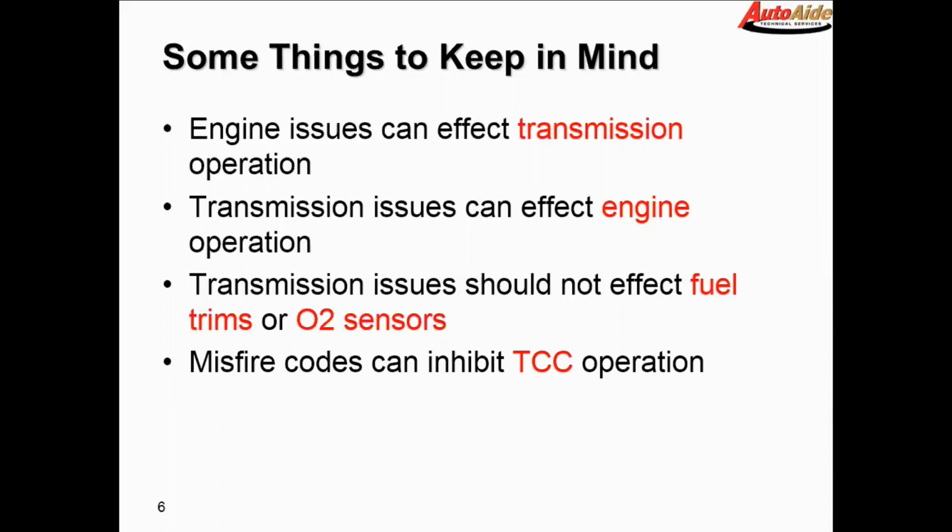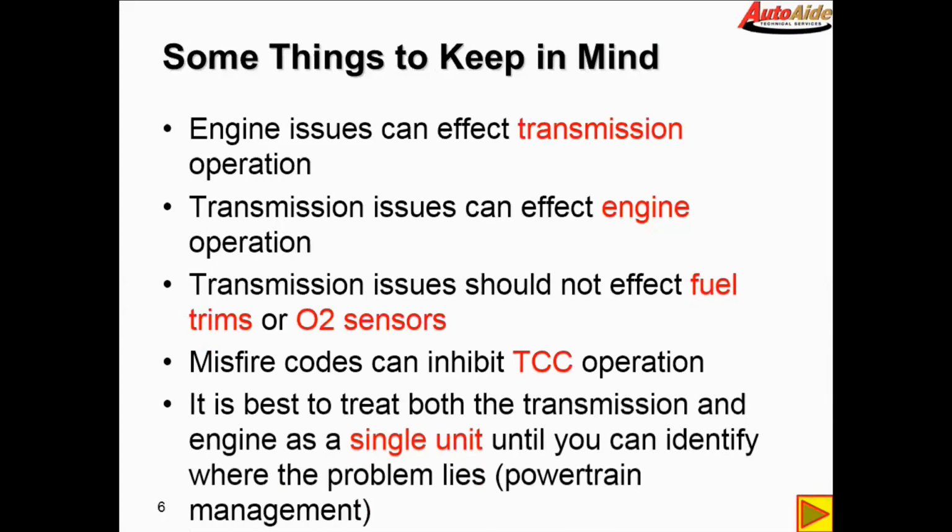Hopefully, if it's misfiring, it's going to set a code for that. But until you can separate out where your problem is, it's best to treat the transmission and the engine as a single unit. Once you've determined that the problem is with the transmission, then you can stop doing that. But until you get your head wrapped around the problem, best to treat them both as a single unit.